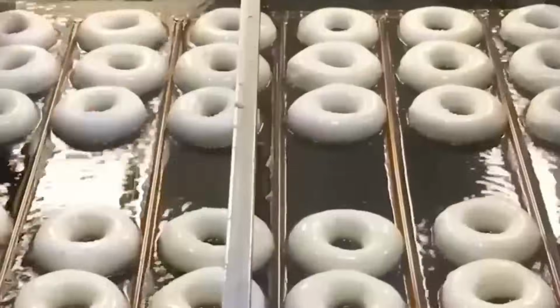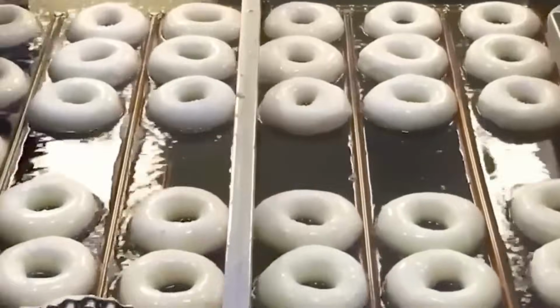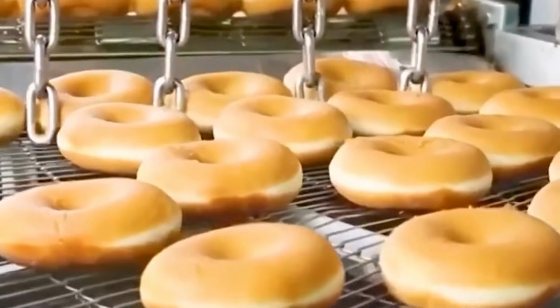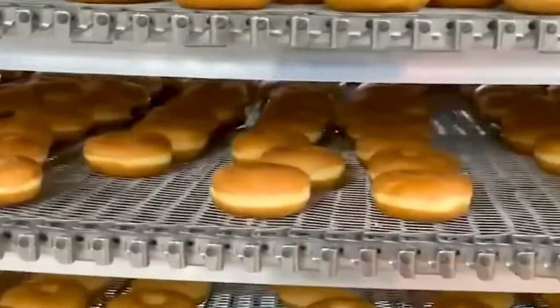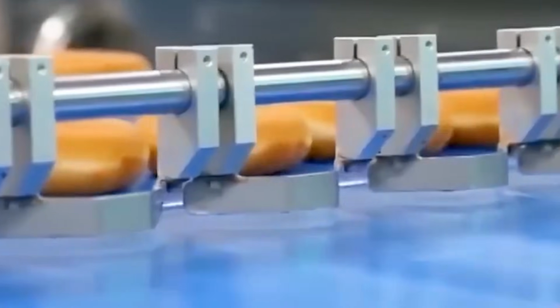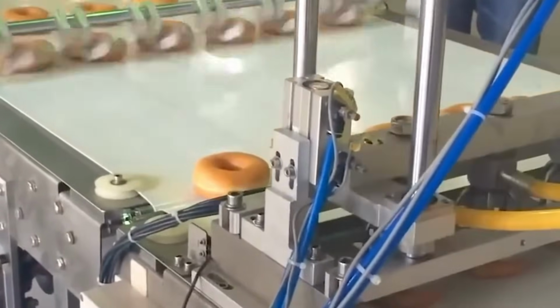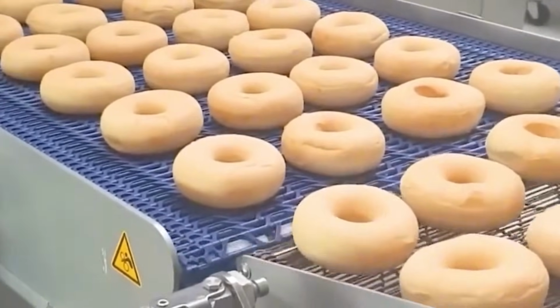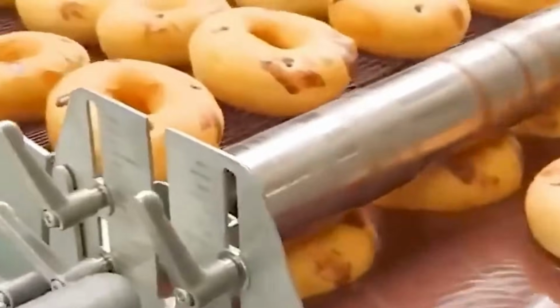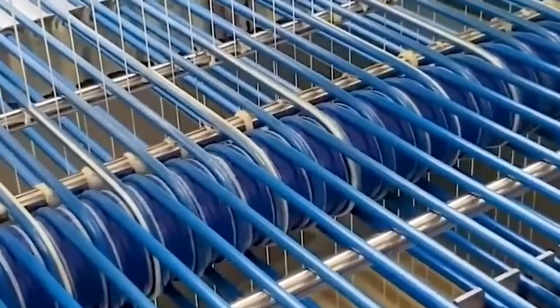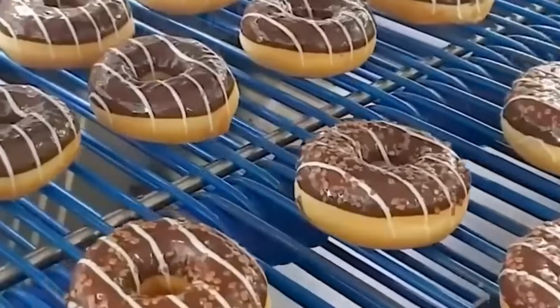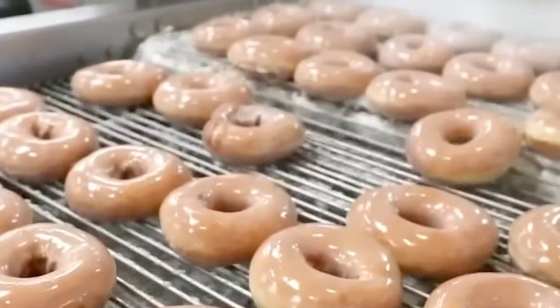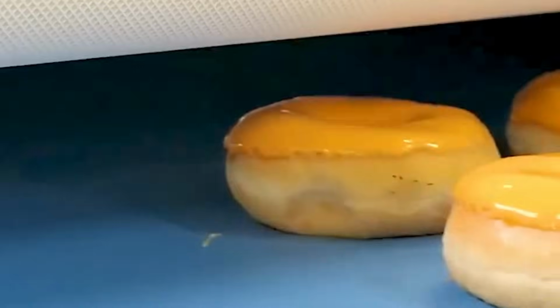Packaged products are conveyed to palletizing stations. Robotic palletizers, equipped with vacuum or mechanical grippers, stack trays in precise layer patterns onto standard pallets. Slip sheets may be inserted between layers for stability. Full pallets are wrapped using a rotary arm stretch wrapper. The film roll is tensioned to apply a tight wrap without deforming the boxes. Wrapped pallets are transferred to refrigerated holding or shipping docks for distribution.